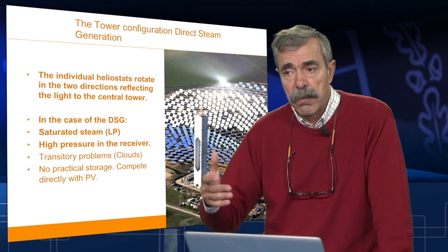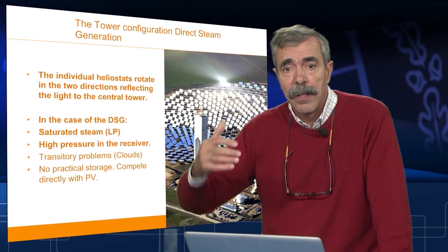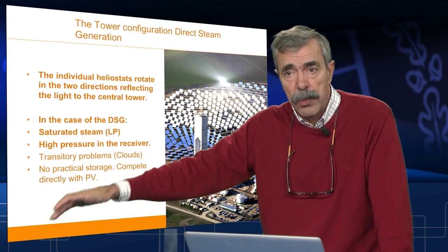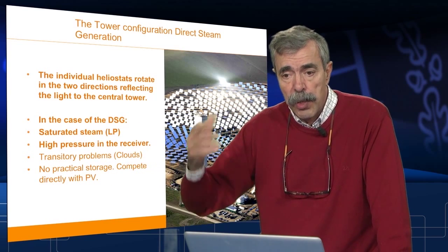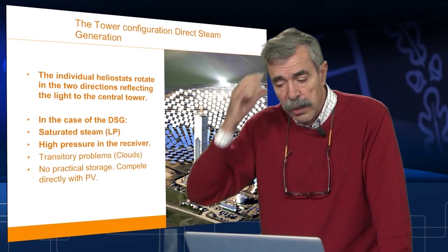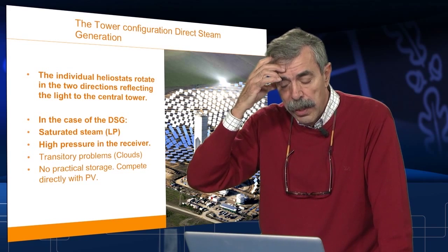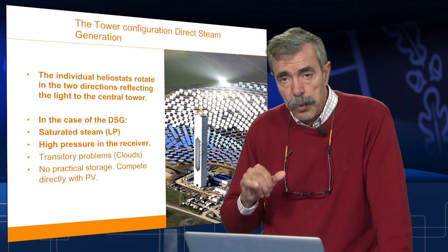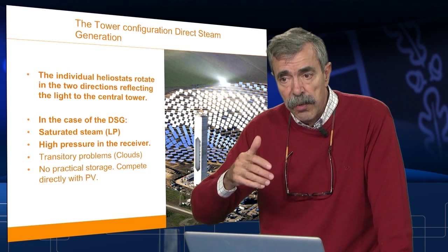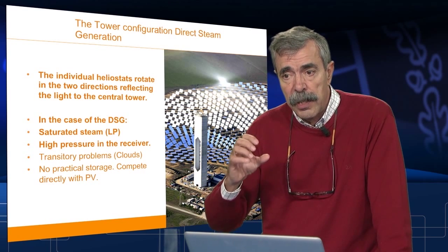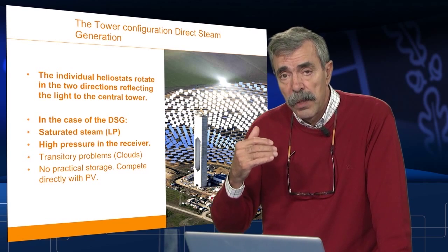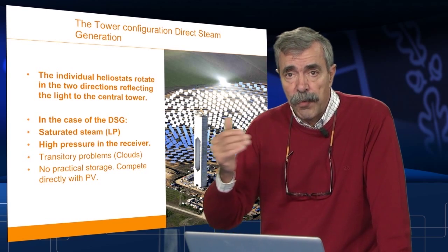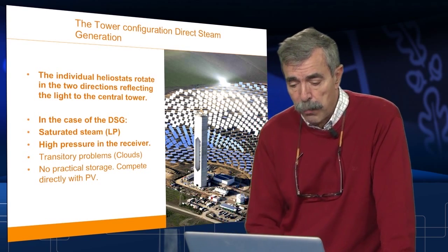A steam turbine needs a gradual descent of the temperature and the pressure. Otherwise, you are damaging the internal parts of the turbine. Those 2 cylinders can contain enough steam to operate the turbine for minutes before stopping it completely.